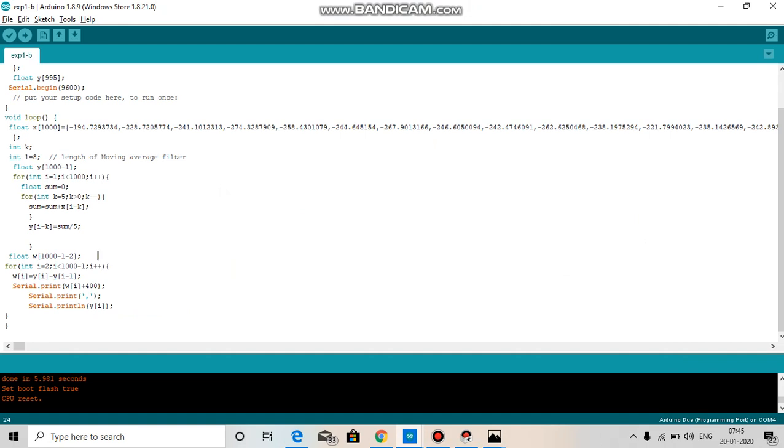In the derivative filter, like in any digital system, there will always be noise due to inherent quantization of the numerical representation format, and therefore it will always be amplified when using the first difference filter. Let y of n equals x of n plus v of n be the signal which we want to filter, with x of n the useful part of the signal, and we often see additive white Gaussian noise of variance sigma square in the bandwidth of interest.